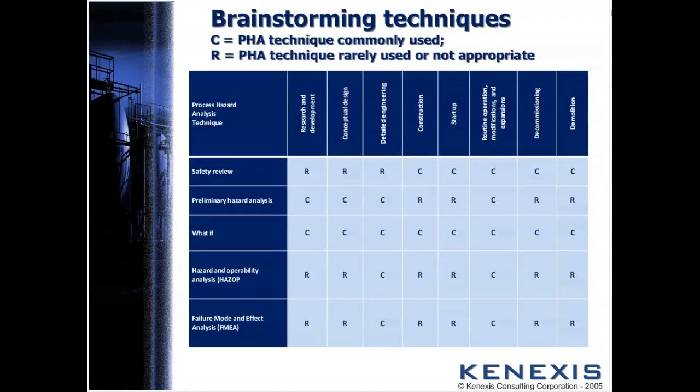If you look at failure mode and effects analysis, I neglected to mention that, but a failure mode and effects analysis is usually used to identify single pieces of equipment and system failure modes, and how each mode impacts the system or plant. This analysis typically generates recommendations for increasing equipment reliability, which will improve the process safety of the plant. FMEAs can be done by a single analyst. We're not going to talk too much about that during this study.